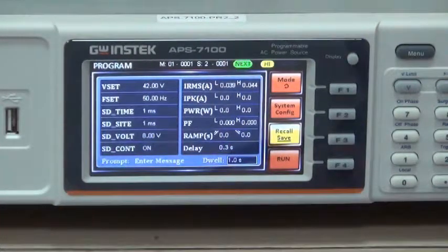Finally, set power supply output conditions for program 1 and step 3. Turn knob to S02, 001 and change it to S3. Enter. Turn knob to Next and change it to End to set step 1 as the final step.